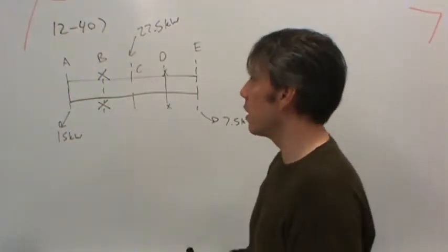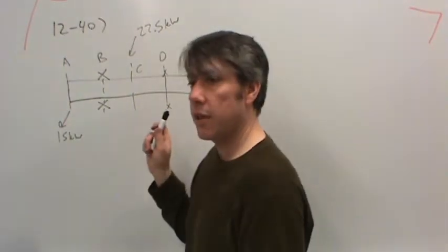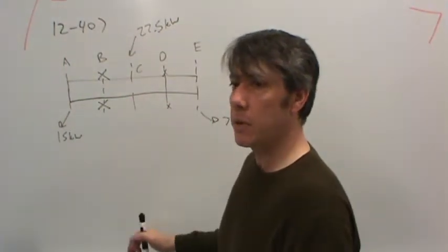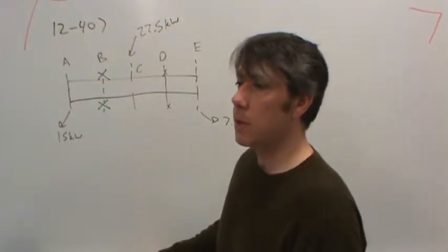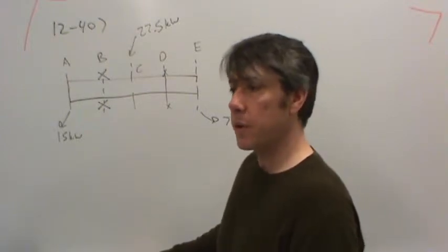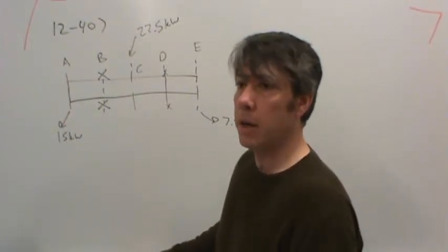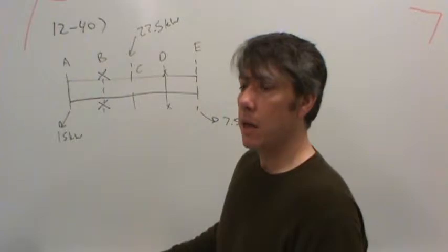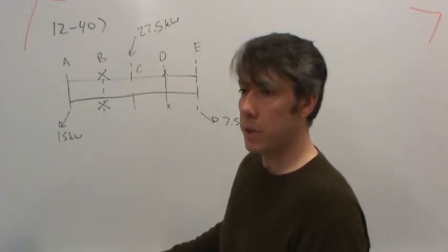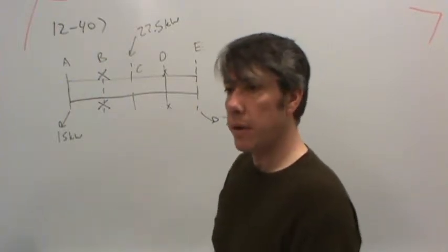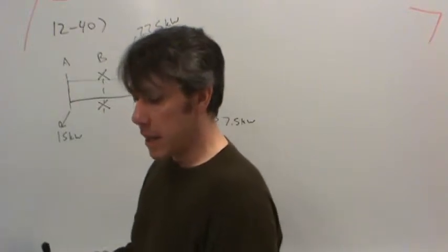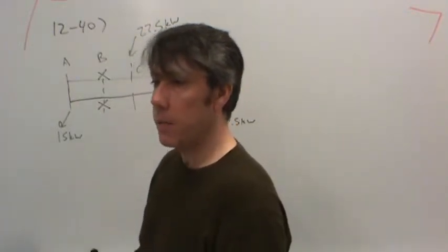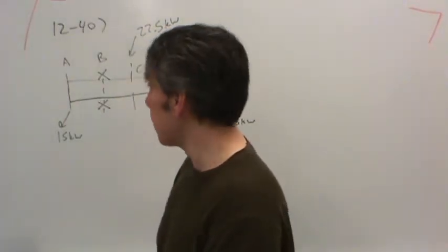That's kind of interesting. This kind of looks like a crankshaft in your car, except with multiple bearing points. It's interesting that you actually lose a couple of horsepower per bearing when your engine's at full speed. As the speed goes down, the power you lose decreases, but as the speed goes up, the power loss increases. But that's a plain bearing. We will talk about plain bearings as well later.